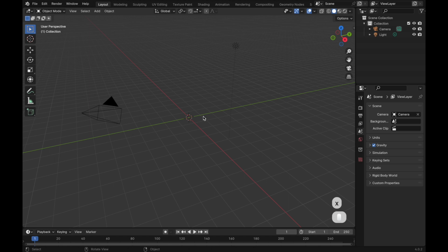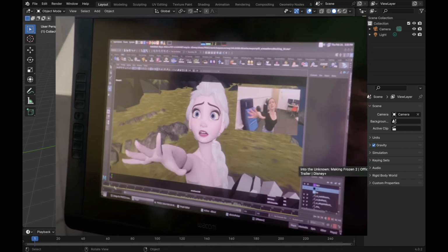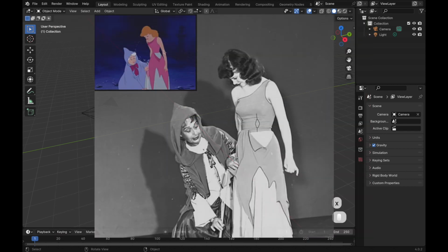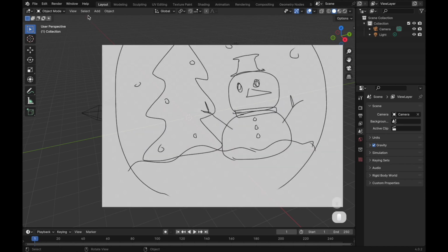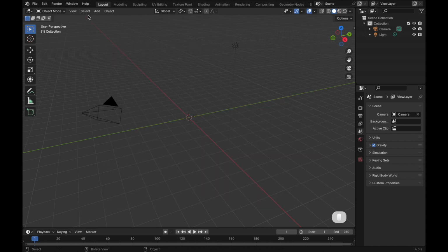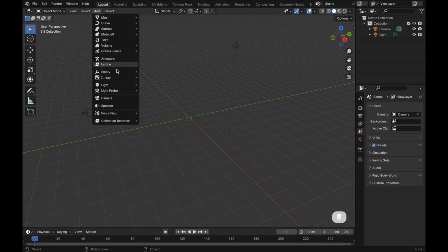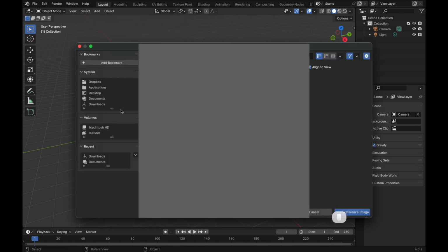When creating 3D models or 2D drawings, a must-have is a reference to the idea of how the end product at least must look like. I have this drawn sketch, which I will be using as a reference for this 3D model. I will go ahead and upload it into the Blender workspace. Select Object, Image, Reference, then select the image file and press Load Reference Image.